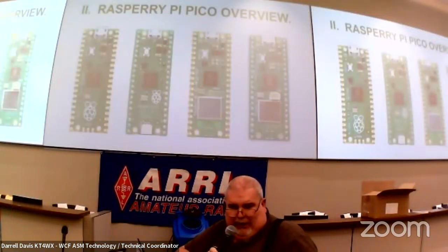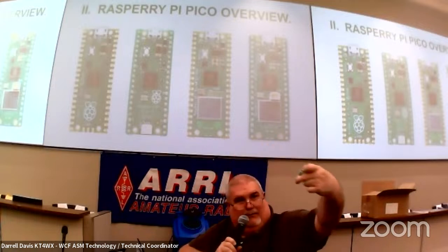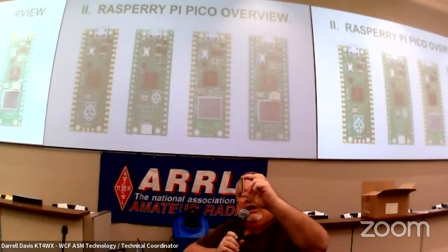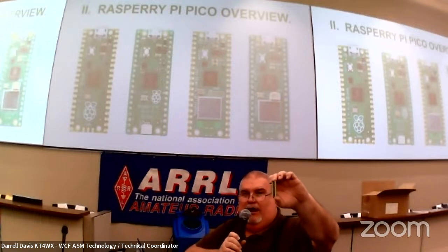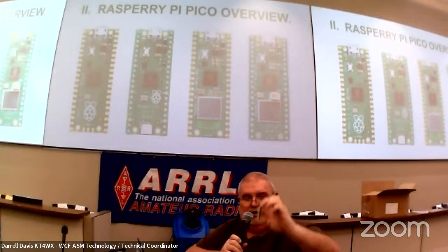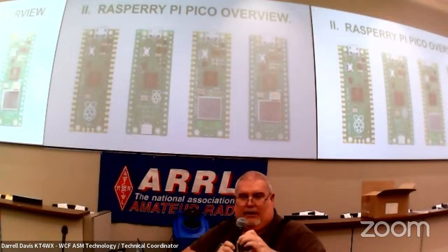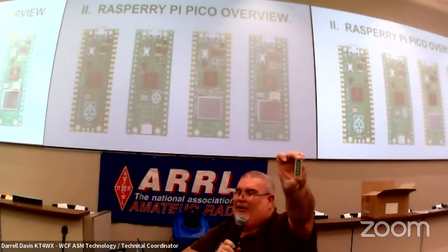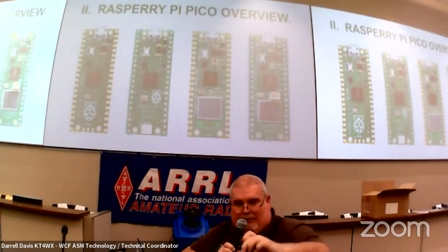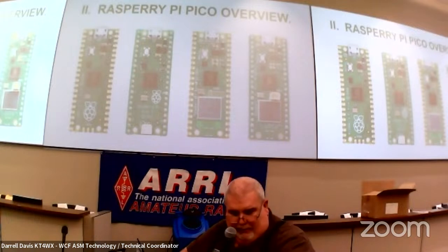And there are the 4 variants of the Raspberry Pi Pico. And there is mine. That's how big we're talking. You say, that looks familiar. You're right, it does. It's a 40-pin dual inline package, DIP header. If you say, I'm not good at surface mount soldering, that's okay. You've got a header on there. You can solder that onto a printed circuit board and make your own project out of it. They put that on there for you.